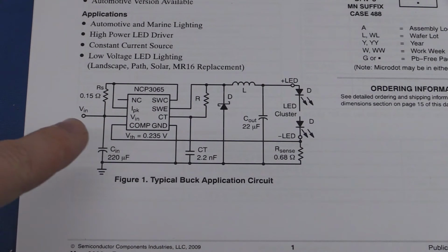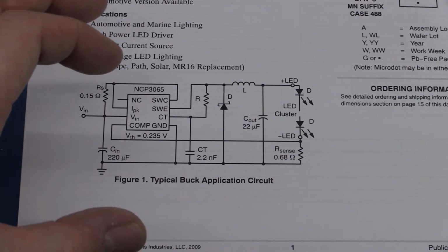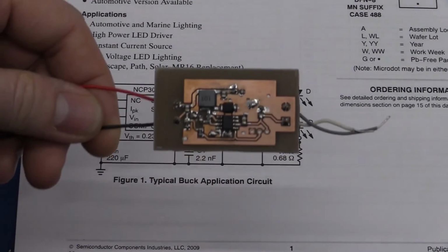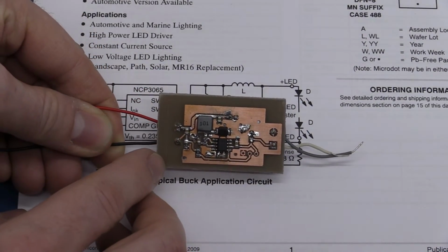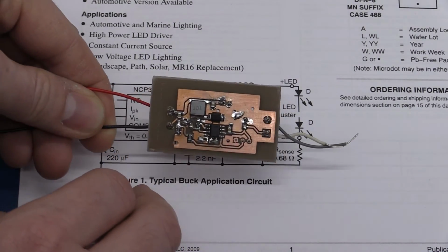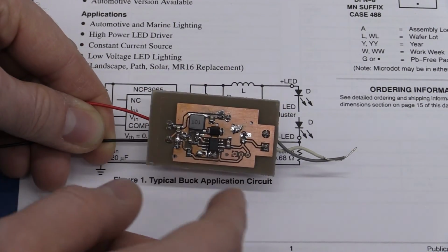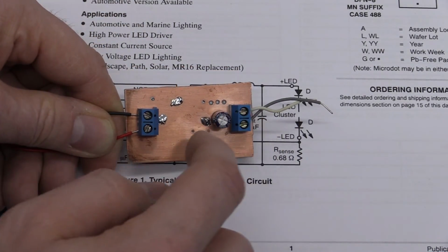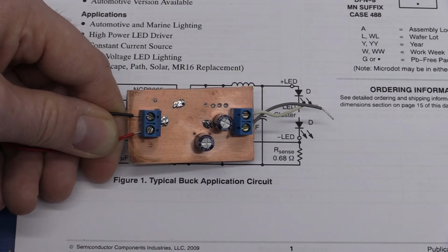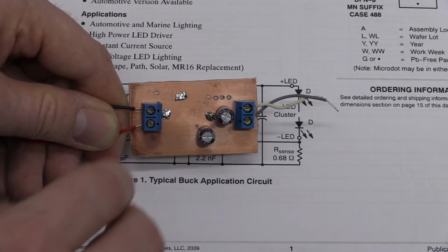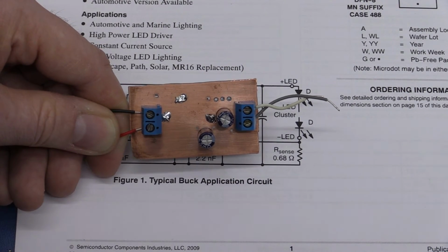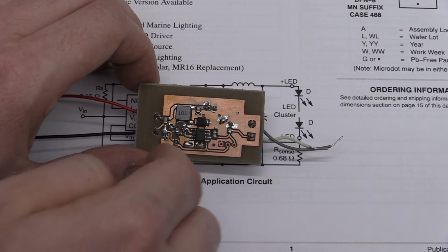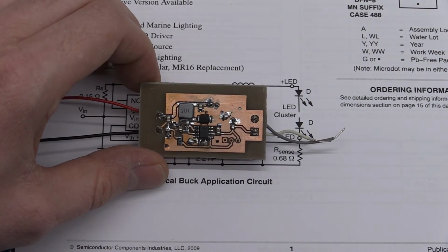I changed the resistor values a bit to give me the current that I need. And then I went to my garage and etched a quick board. It's not really that good. It's basically just a single layer board with a ground plane on the back also, and then 2 capacitors. There's no traces on the back, so I just drilled through and removed the copper around the holes. Some of my ground plane got trapped on this side, so I had to drill through and make some vias.